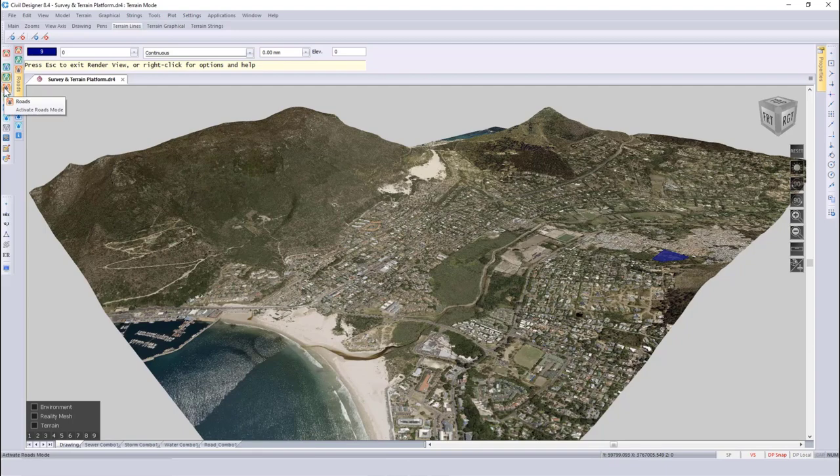We'll then move on to the roads module, where we'll look at numerous different options, including the Masshaul, the Cumulative volumes, your Layerwork volumes, including road rehabilitation functionality, things like your Kerb Quantities. We'll then end off with the different pipe modules, so the sewer, the stormwater, and the water.